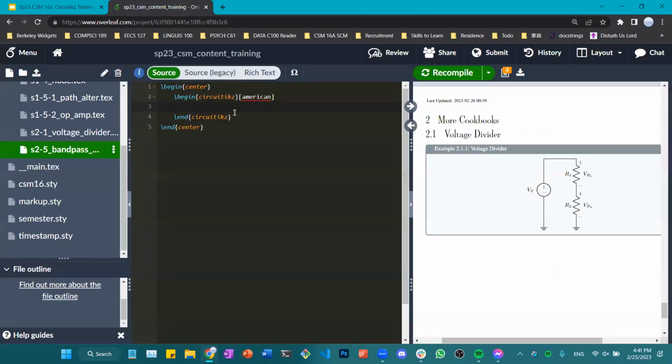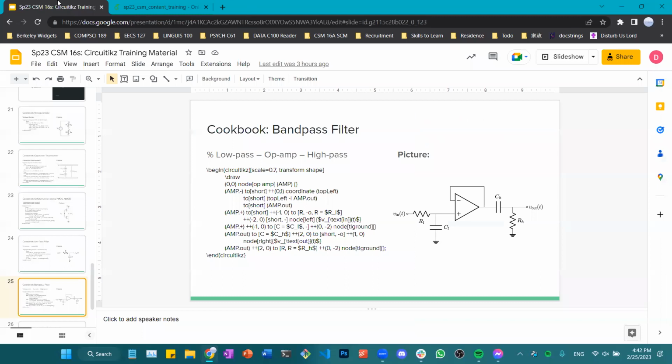So I'm going to first define a node at 0, 0 once again, because it's easier to deal with. I'm going to call this node M, just to keep the convention going. Once again, it has to have a curly bracket. Okay, and I'm going to start something from maybe the negative side of the node. What the negative side of the node does is this thing that we've seen in an inverting amplifier, right? It does this rectangular shape and then goes back to the out.